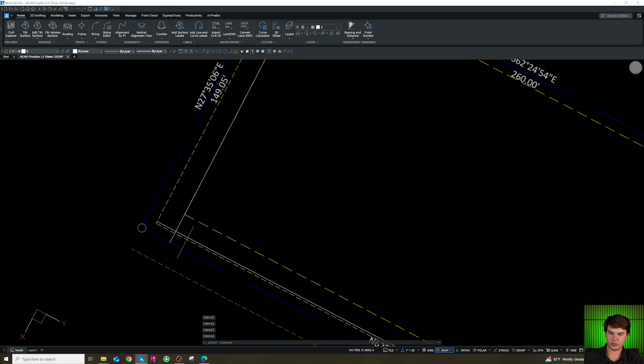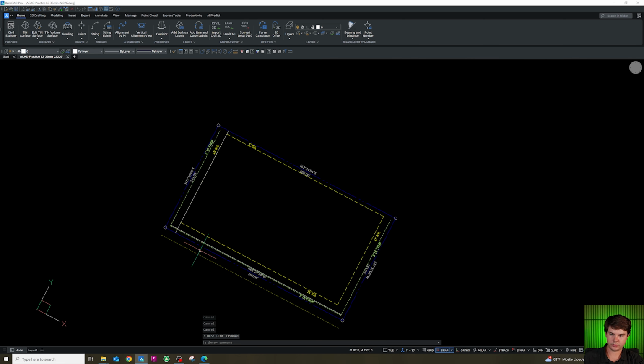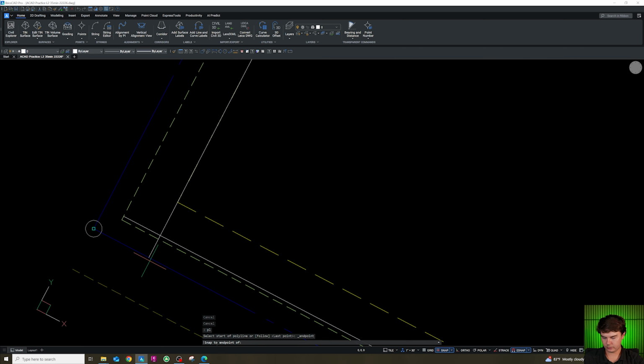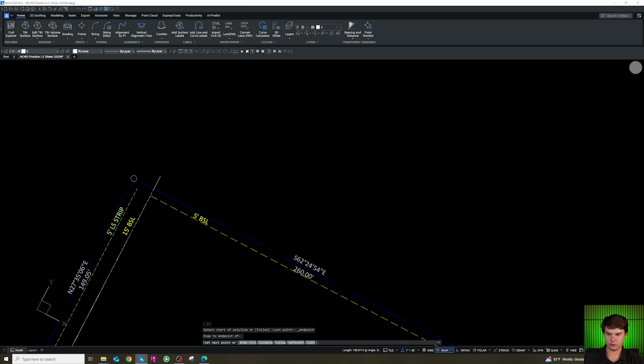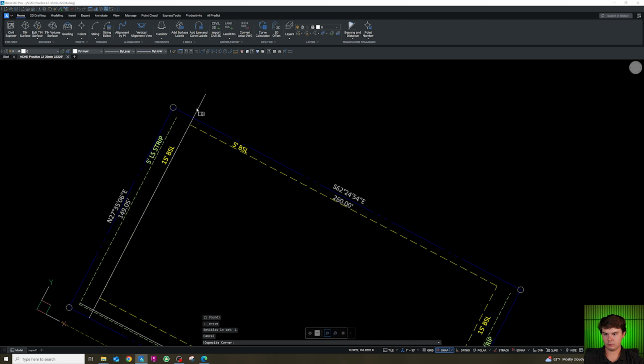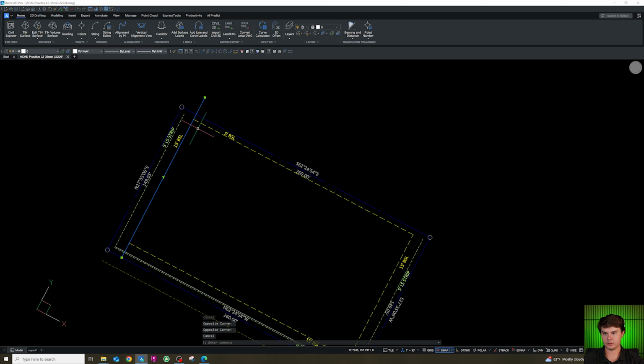And just to make sure that all our drawings are ortho to this main property line, I'm going to redraw this line orthogonally to the property line. So now we know that this line is exactly 90 degrees from our property line, and it's 15 feet from the side. And here we're going to want a 37-foot drive aisle, so I'm going to offset this 37 feet.